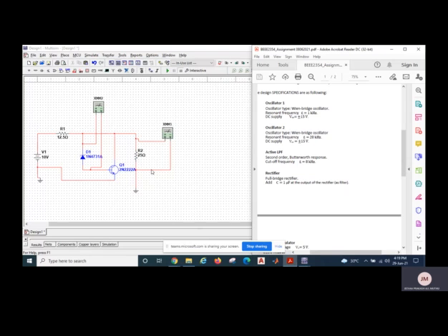This method uses a number of fixed voltages, and for this circuit I have used 10 volts. It is apart from the main circuit. For conducting this, I did 10 volts, and we have used 13.8 for the main circuit. The relatively inefficient main regulator can then be used in the power supply unit, because each section of the circuit has its own regulators.